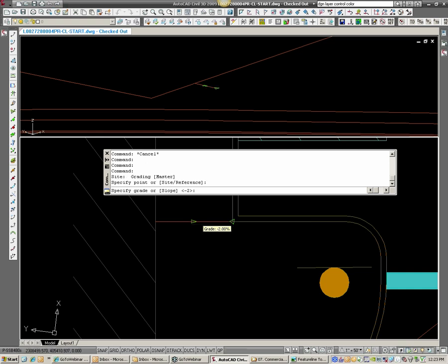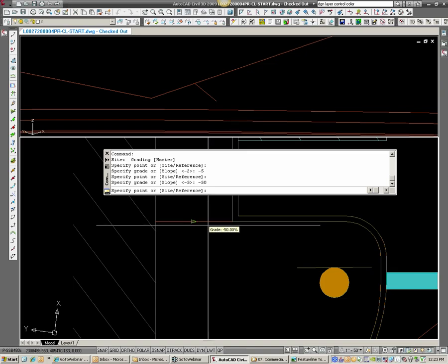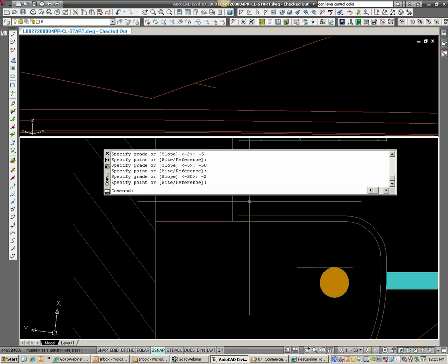So that's a nice little tool to read and verify what slopes feature lines are at, or change them. I can go ahead and click on that and watch up here in 3D view, and I can say change that to -5, and you'll see that line move down a little bit. For a more drastic representation of that, I'll do -50. You can see it slides way down. But I just want to keep that the same, so I'm going to do -2. Bring that back up. Hit OK.